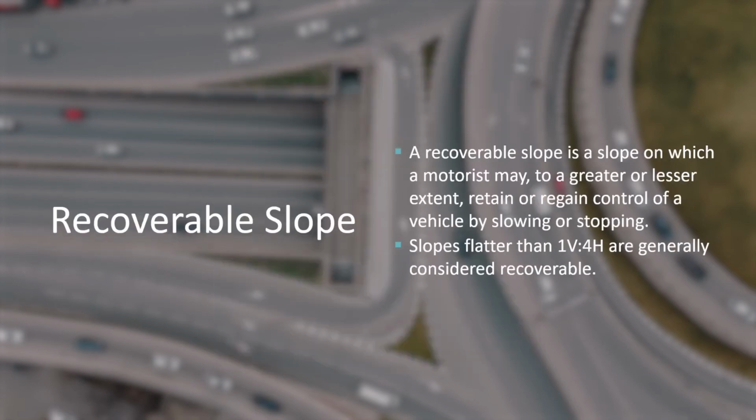A recoverable slope is a slope on which a motorist may, to a greater or lesser extent, retain or regain control of a vehicle by slowing or stopping. Slopes flatter than 1 vertical to 4 horizontal are generally considered recoverable.